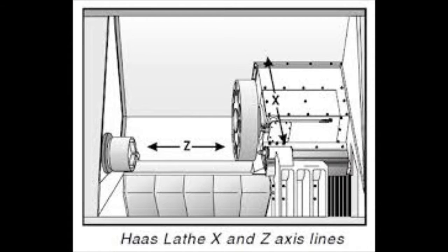Well, let's remember that the lathe has just two axes. The Z-axis, which moves horizontally, changing the part length characteristics, and it is limited by the length of the part, from the chuck of the machine to the part 0. And the X-axis changes the part in a revolving way, cutting it as it rotates. It's limited only by the radius of the part. You can see in the image on the screen how these axes are distributed.